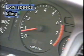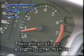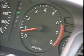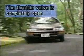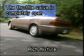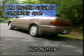When the engine is idling, or when the vehicle is traveling at low speeds, fuel and air do not mix well. Because of this, it is necessary to achieve the theoretical ratio, or a slightly richer mixture. A greater ratio of fuel to air is necessary to obtain the needed power when climbing hills or other times when the throttle valve is opened wide.